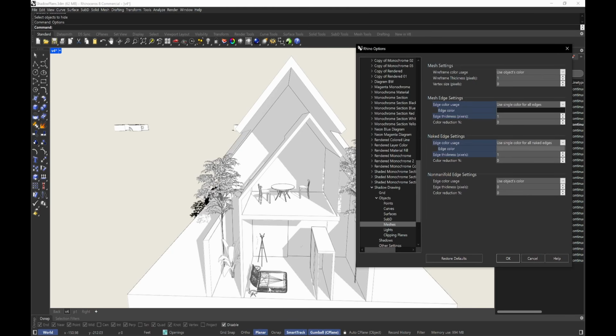So you want to try to find a pretty simple mesh that you can use. Like actually this tree mesh is more simple than this bed block, for example, or even this little plant that you see here is more simple than this bed block. So this is a bad example of types of blocks you don't want to have in here, okay? And again, this is in the scenario where you only want to stick in Rhino, right? If you're going to take it into Illustrator, I would recommend not to screen capture or view capture to file the blocks in this view. I would just keep it only on Make 2D when you overlay it. And I'll show you the Make 2D and how I overlay it in Illustrator as well. But I just want you to understand this is very important when it comes to mesh settings, okay?